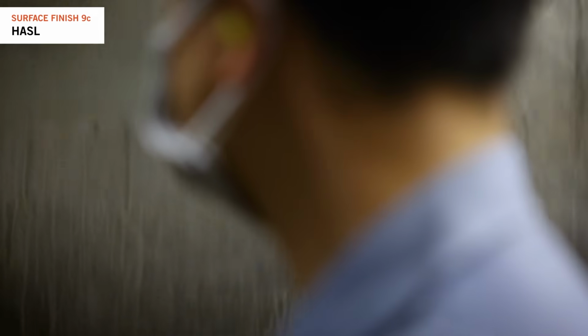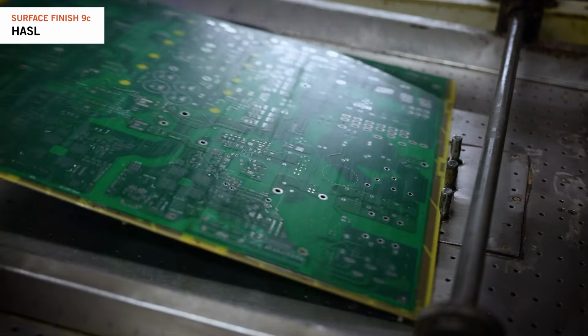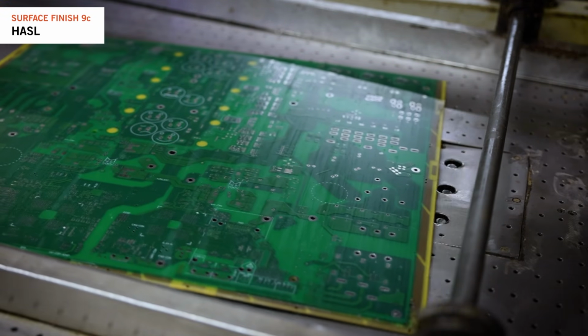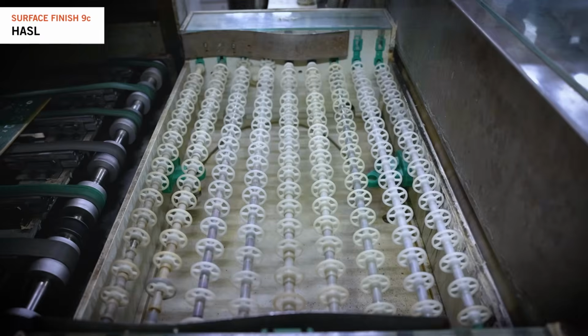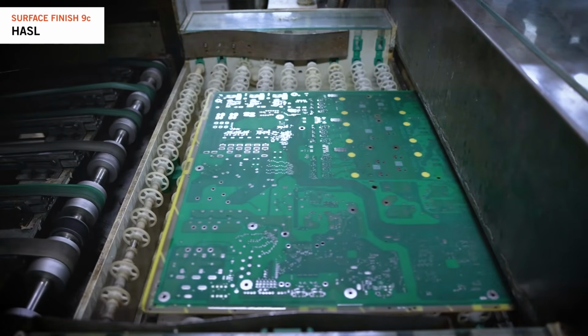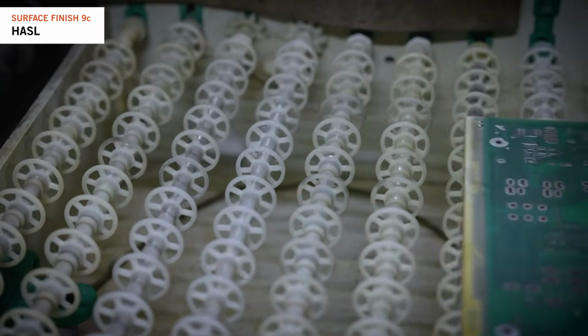After that, we clean the PCBs to remove any leftover flux that could cause corrosion or electrical issues. It's important to control the copper content in the solder bath and remove impurities to maintain a good solder surface. It should be noticed that this principle is the same whether we are running a lead-free or a leaded HASL. Of course, some of the temperatures and other parameters may change, but the principle remains.